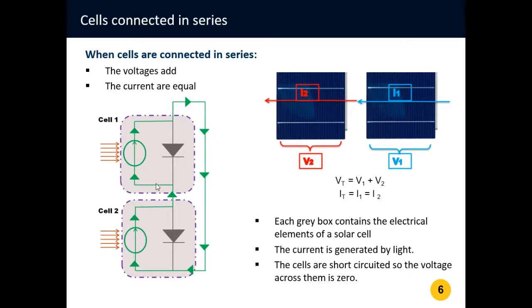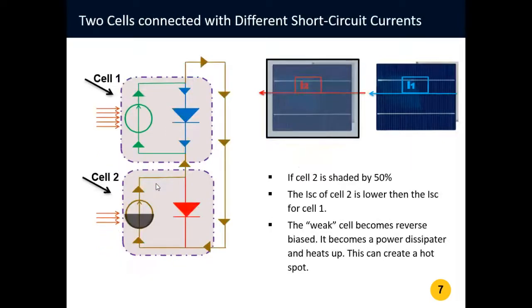Here we're in a situation where one of the cells is shaded by 50%, for example. This shading could be due to a number of factors. It could be literally shade on a cell, shade from another building or a tree, or some form of vegetation that's blocking the light to that cell. Or it could be shaded by soiling, which is dust accumulating on the modules.